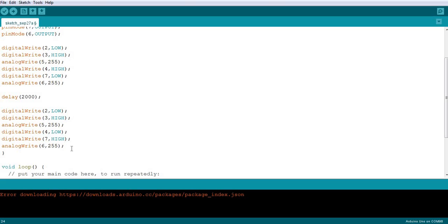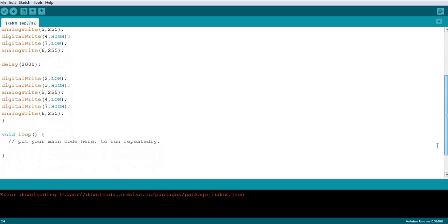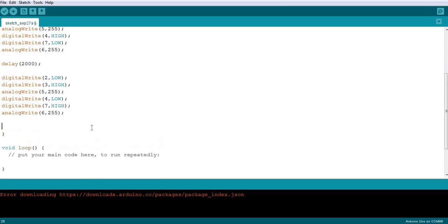But a hard right turn also needs a specific amount of time. So these commands need to execute a little longer before the next action starts. And for that we need a delay. With our experience, we know that a delay of 650 milliseconds is sufficient for a 180-degree turn.